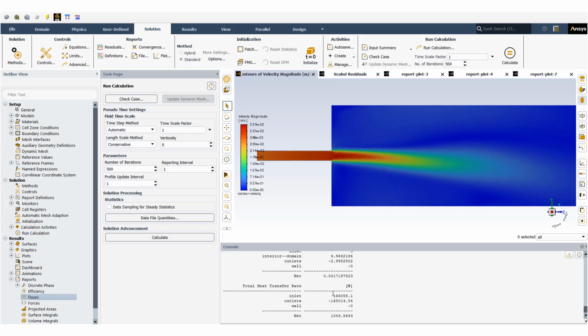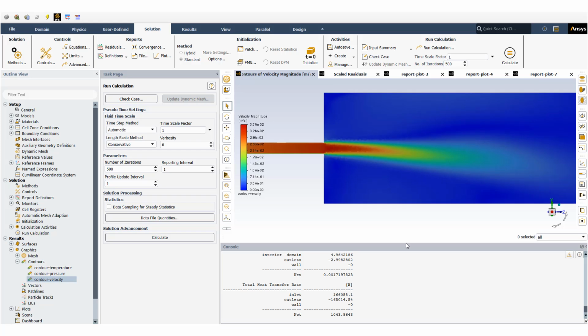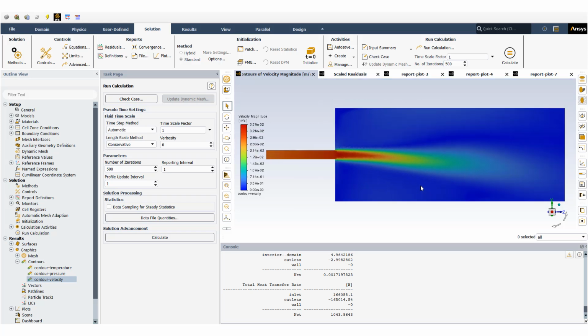We can run this model further to see what's going on, but the intention in this example is to show that when we have sudden expansion of the gas volume, we can use this technique in industry for cooling, for temperature drop, and this happens without any input energy to the system, which is good and makes it one of the good candidates for industrial cooling. So I hope that by this example I could show the proof of concept of the adiabatic cooling due to the adiabatic expansion. Thank you very much for following along with this example.